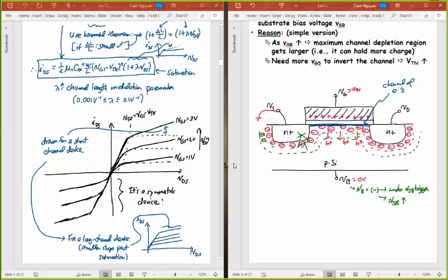Basically I'm putting more negative charge here, and it's all static negative charge due to atoms that cannot move freely in the lattice, but we've taken holes away from them, or alternatively you could say that they've absorbed electrons. That's part of the more physical thing that's going on. In this case, what I've basically done was put more negative charge in the p-type silicon here.